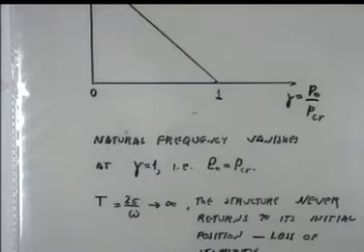That is what buckling is. It leaves the equilibrium state and never comes back. Do you remember? That is what we talked about. The system suddenly gets deflection, another position. It was straight, and now it is not straight. And now vibration says not only is it not straight, but it never comes back to this straight position.